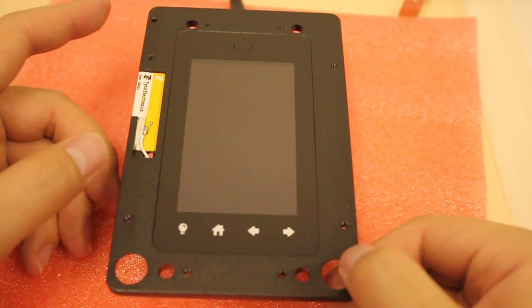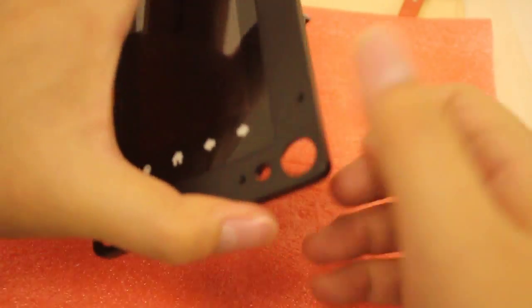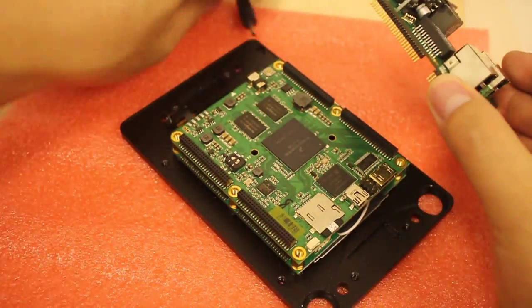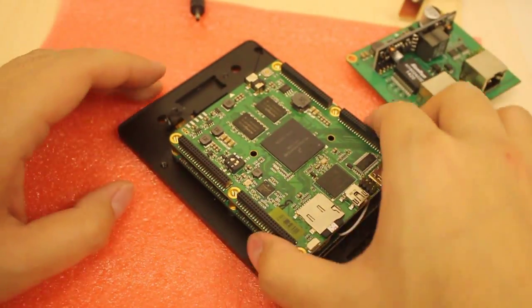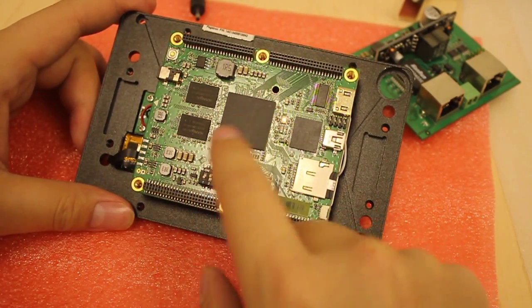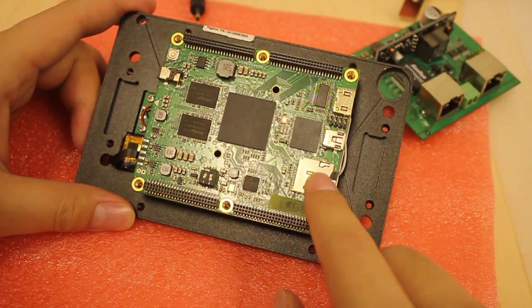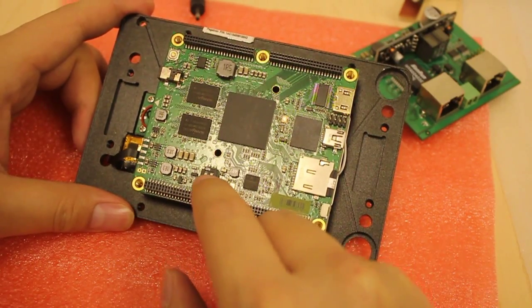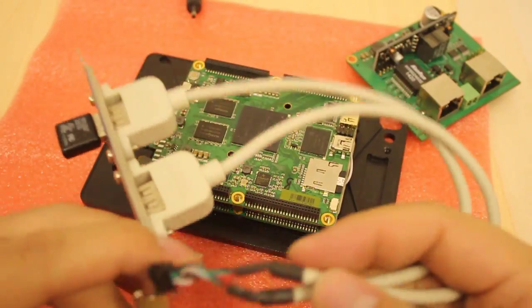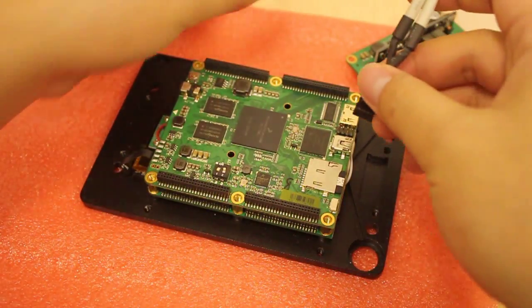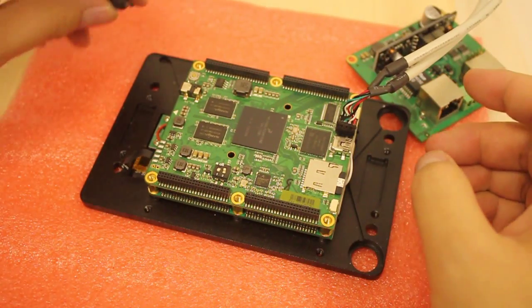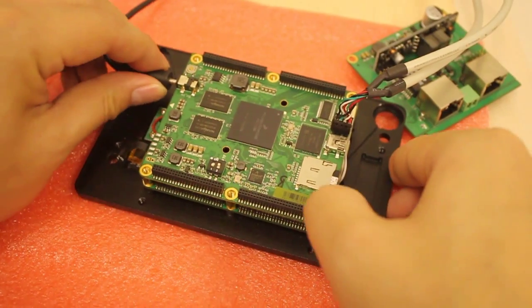So right here I have the 3.5-inch wall pad. Instead of using the PoE, I'm gonna use the 5-volt adapter. And over here we have 2 switches. One is for boot up from the internal storage, and the second one is for boot up from the SD card. So we're gonna choose number 2. Also, I have a USB adapter, and I plug it in over here so I can control the device with my mouse and the keyboard. So power it up.